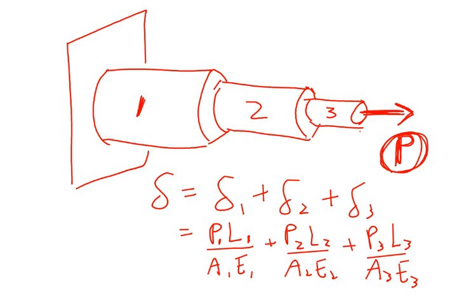But formally, okay, how do I find P1, P2, and P3? This is mechanics of materials, right? Obviously. And I have mentioned in your very first lecture, right, our previous lecture, that when you calculate stresses, your stresses are force per unit area, but that force that you're referring to is the internal force acting on your part. Okay? We never, ever use external forces to determine stresses.